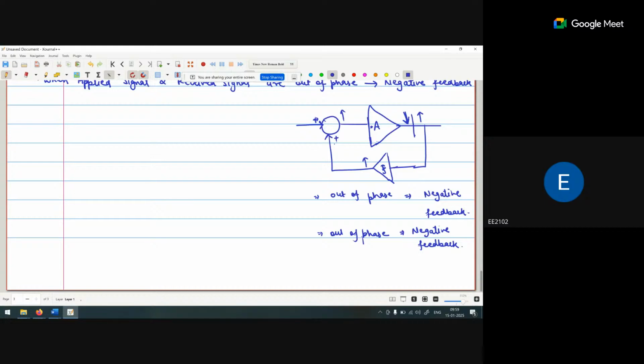Like AC. If I insert a sensor in the AC, my feedback system is the automatic feedback. Why? Because the sensor will sense the signal and compare it with the decided value, 25 degrees, and according to this it will generate a signal. Manually, what will we do? We have a remote. When the temperature is equal to or less than 25, I just turn it off. If it is greater than 25, I turn it on and the AC will start working. So if I control this in a manual way, it is a manual feedback system. If it is controlled through a sensor, it is an automatic feedback system.